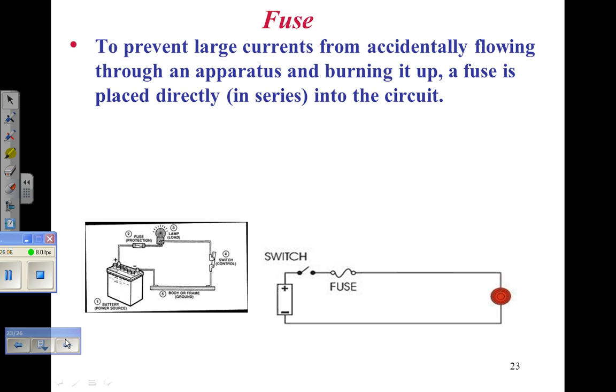The circuit breakers in your panel at home are what are called either instant trip circuit breakers or inverse time circuit breakers. And now you're wondering, which one do I have at home? You have an inverse time circuit breaker. That means that if you have a 20 amp circuit breaker and it is pulling 20.02 amps, how long will it take to kick off? It probably will never kick off. Probably never. It's not that accurate. How about 22 amps? How long will it take to kick off at about 22 amps? It's about running about 10% over.